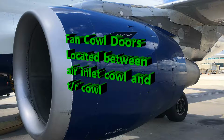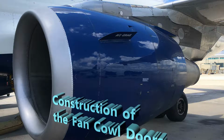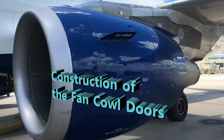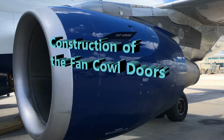The fan cowl doors, just to get an idea on the construction of them. There are 4 frame stiffeners on the inner surface of each of the doors. That's just to give them that strength. There's 4 attachments. There's 3 aft that are fixed from the pylon, and then you have a forward hinge that's free floating, but it's also connected to the opposite fan cowl door. There's 4 latches that secure both the doors together, and those are located at the bottom, to close around the compressor case.